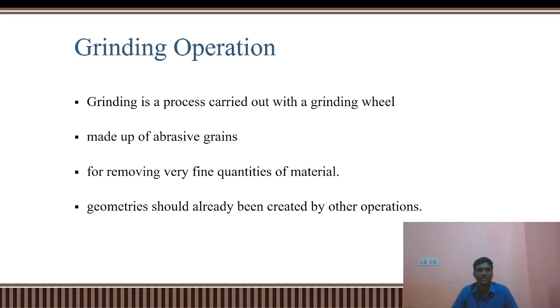And the last point was important. That means these grinding operations are considered secondary operations, and the primary operations, like additive manufacturing and other CNC milling processes, come first. I'd like to give an example. If I want to make a part prototype, first of all, I would go for other operations like additive manufacturing. If I make a prototype using additive manufacturing, the surface accuracy and the surface roughness are very poor in those processes.